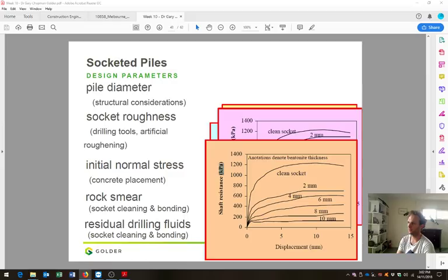Well, air flush is using air to blast out the debris that's being drilled, and water flush is using water. Air flush generally doesn't disturb the anchor hole as much as water, so we usually get a larger bond stress. Water also creates a big mess of wet, watery slurry mud when we're drilling our anchor hole. So air flush is probably the most common method in Melbourne. Air flush will also handle much higher strength material than water flush methods.